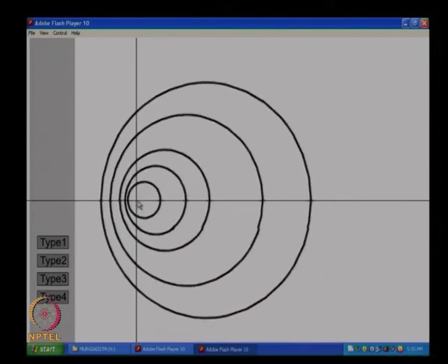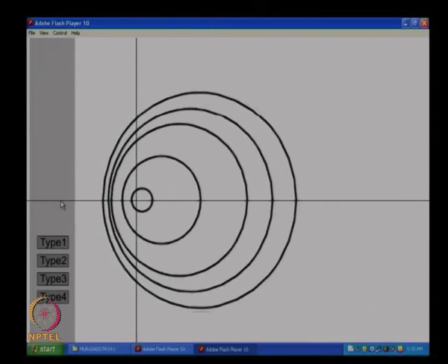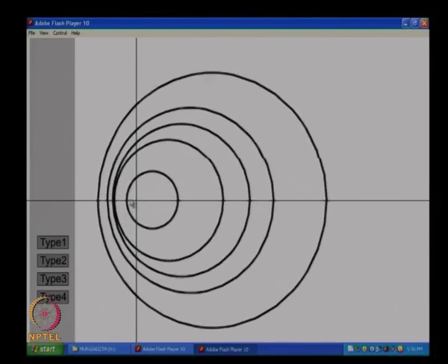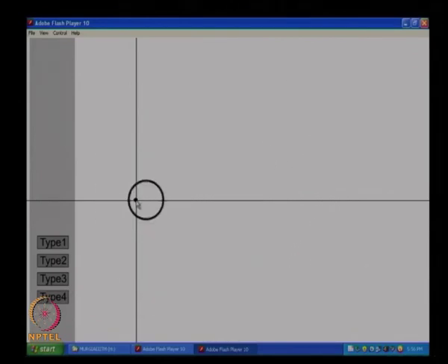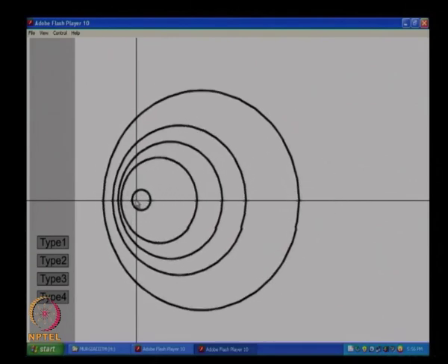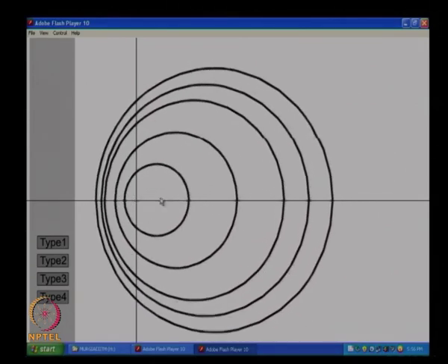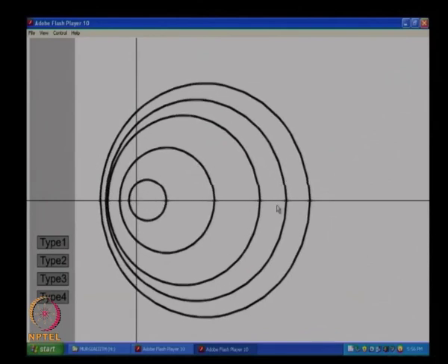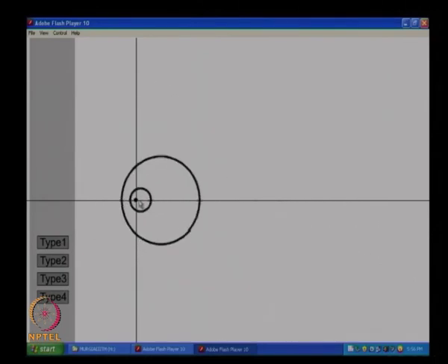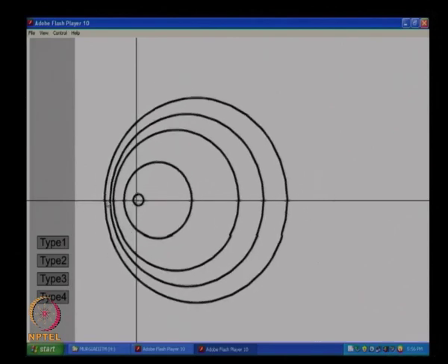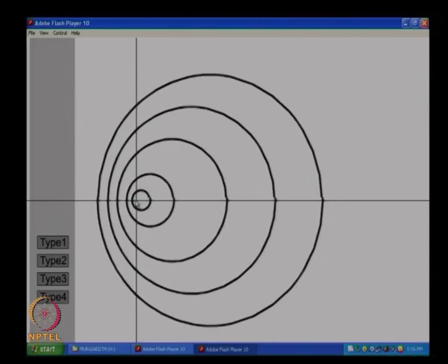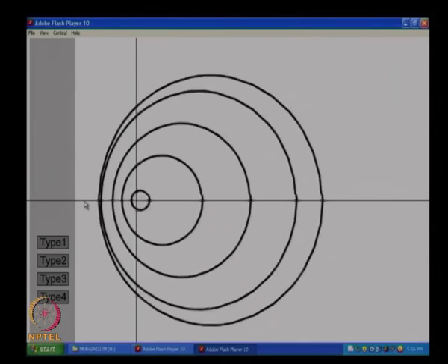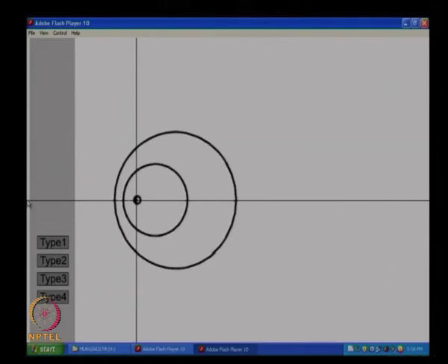It so happens that waves are travelling against this way, and as they go, the fluid is pushing the waves back this way. On this side it is still the same frequency of waves created, but it looks like this, getting crowded here and farther apart on this side. It so happens that the velocity is not very high compared to the rate of travel. You want to call it subsonic flow. The velocity here is lesser compared to the speed of these waves in this fluid. That is what is happening here. Flow is only along this line.